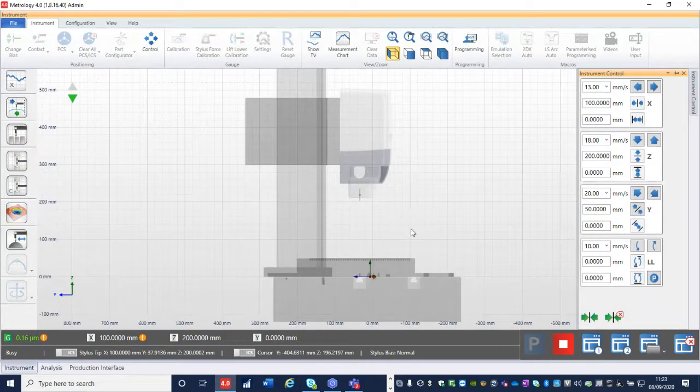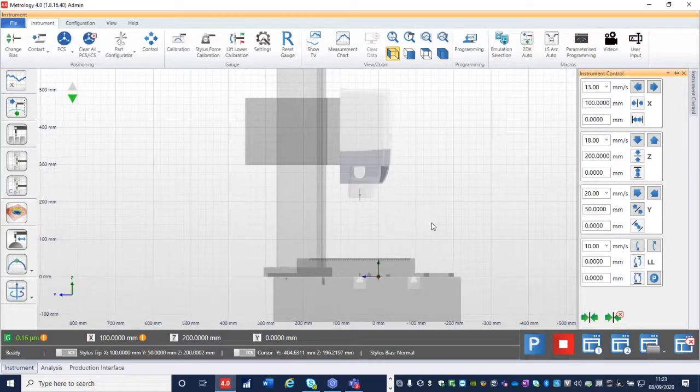And you can see, although the global coordinate graph is moving, what's actually happening is the stylus tip is moving away from the part coordinate to a 50 mil position. The reason it's slightly different in Y is because instead of the stylus moving, what actually happens in reality is the part moves because it's on a Y stage table.